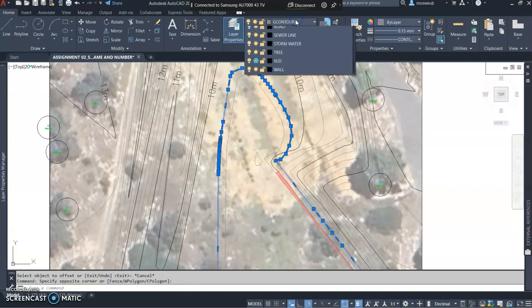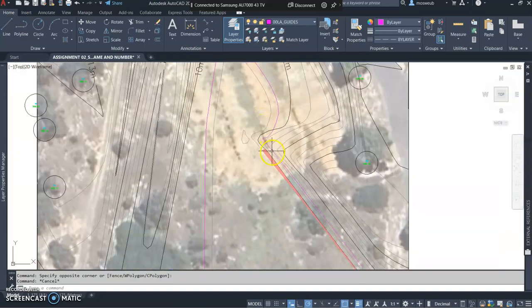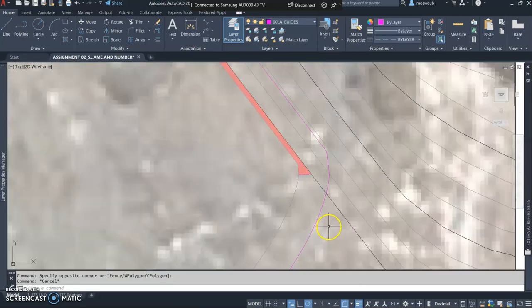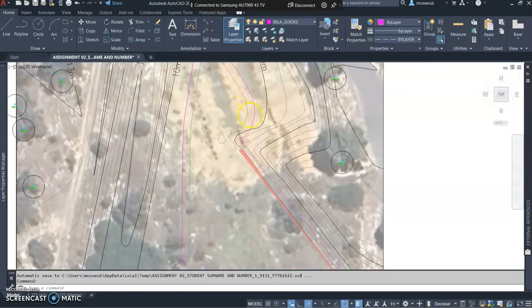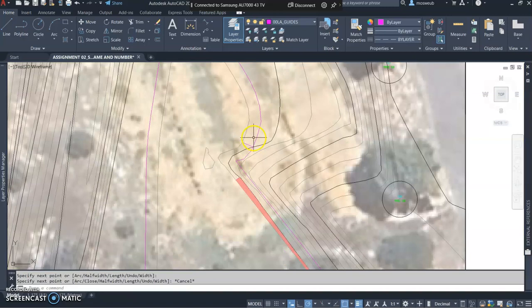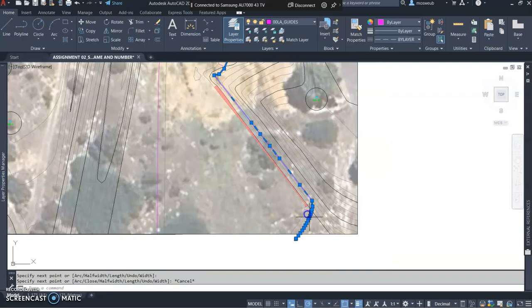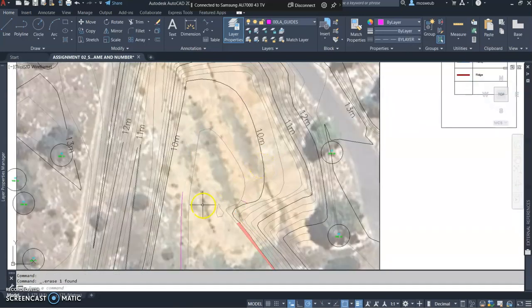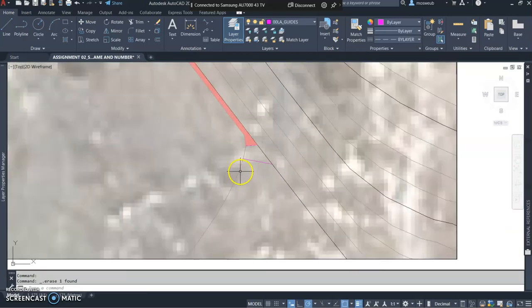Select that particular offset and then allocate it to the guides layer, and then look for every intersection at a 2-meter horizontal distance with the next contour. And then you can just draw the connecting lines and connect them at a perpendicular angle. And then once you've allocated all those areas, just delete the guide, and then you can create your boundaries.